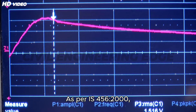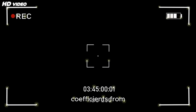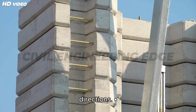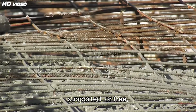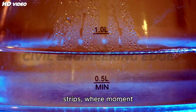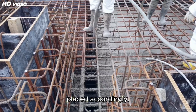As per IS 456:2000, design is carried out using moment coefficients from Annex D for different support conditions. Main reinforcement is provided in both directions. Edge conditions, such as fixed, simply supported, or free, impact the distribution of moments and reinforcement. The slab is divided into middle strips and edge strips, where moment concentration varies. Reinforcement is placed accordingly.